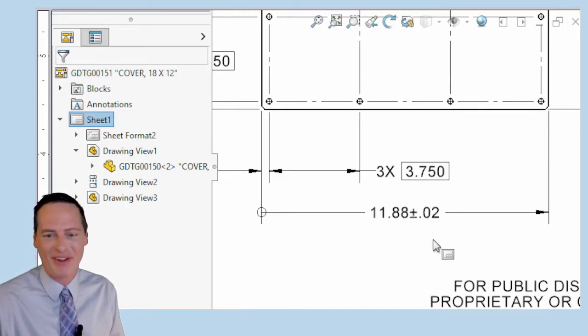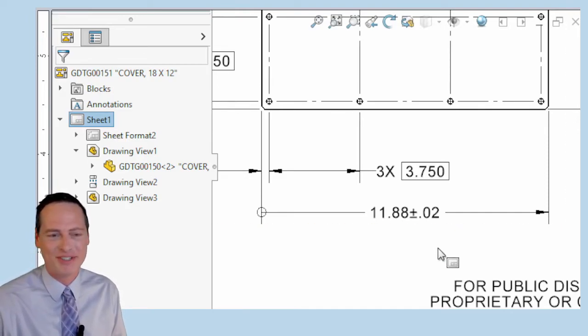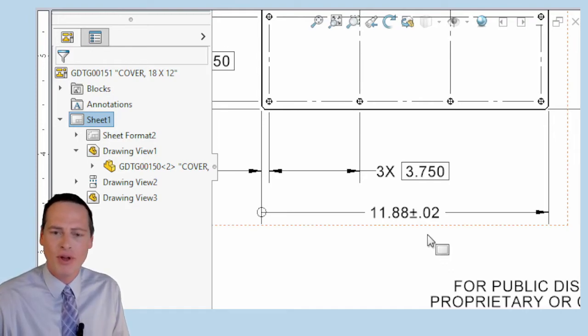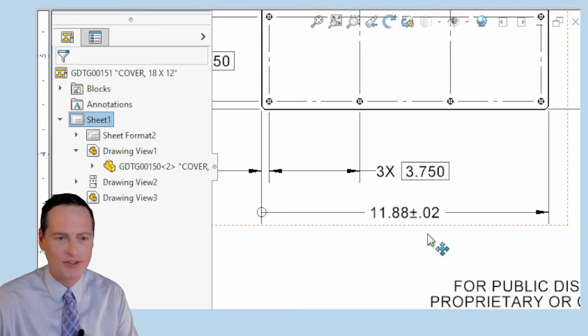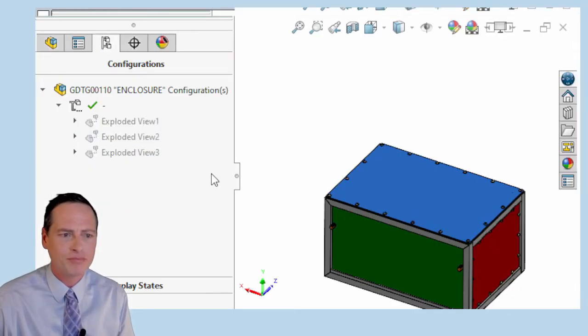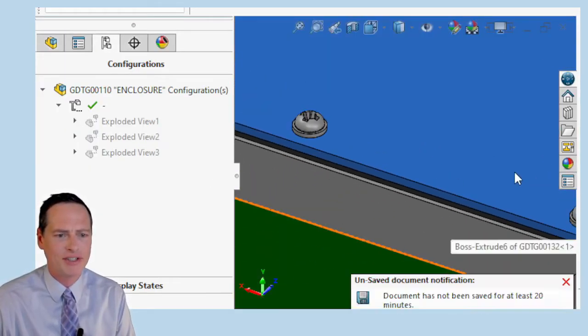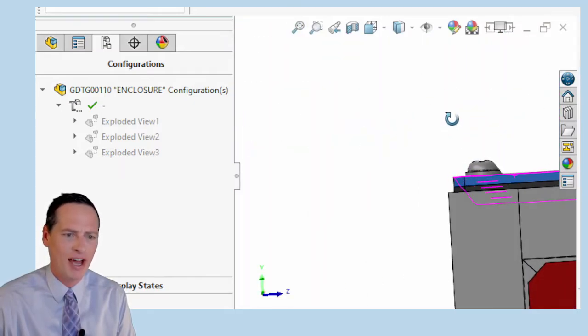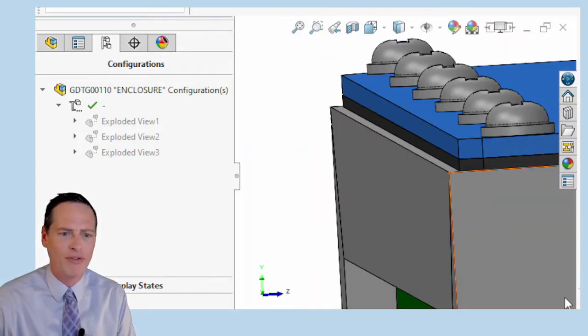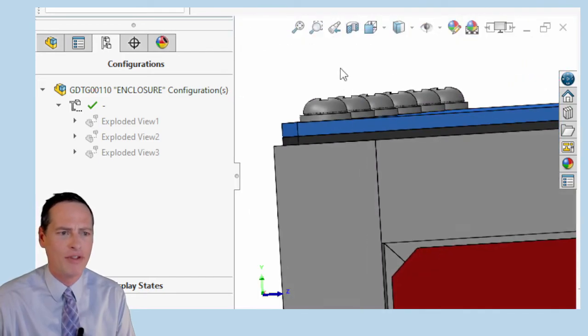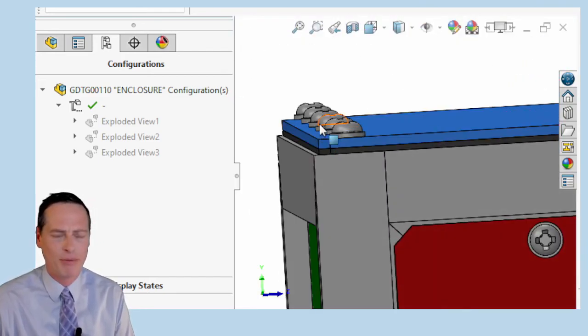and this is kind of a good designer tip. Hope you guys do this. I hope everybody does this. So when you put a cover on something that's 18 by 12, maybe you want to bring the edges of that in a little bit, so their nominal size is inboard of the edge of the assembly below it.